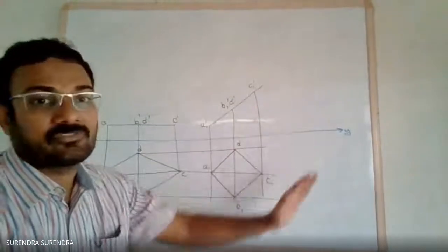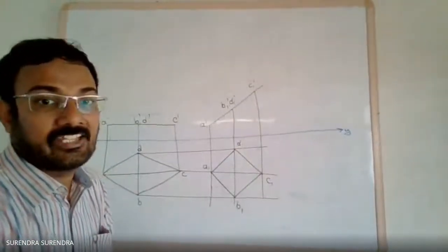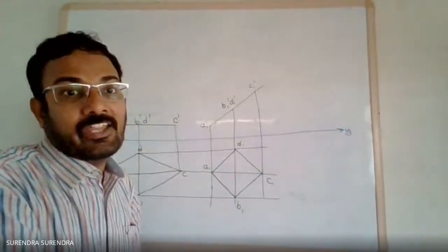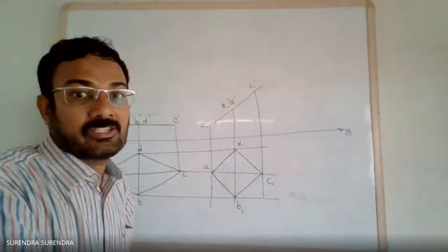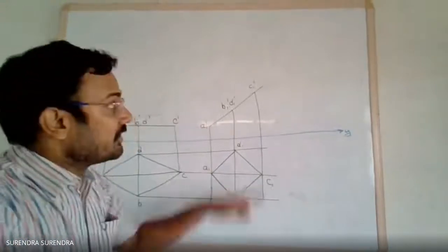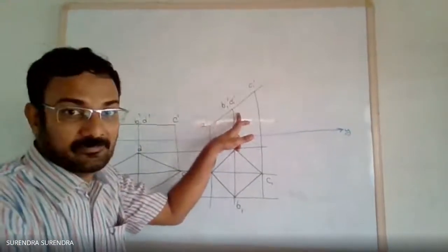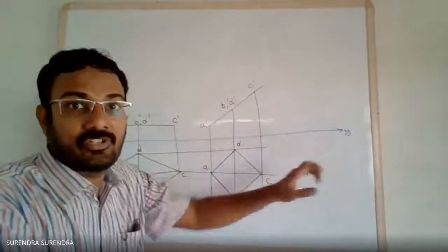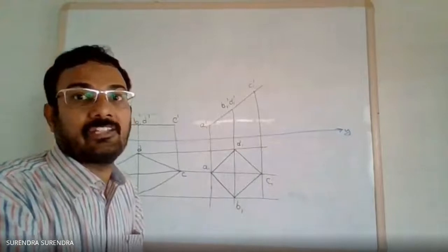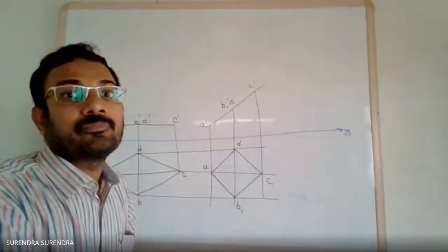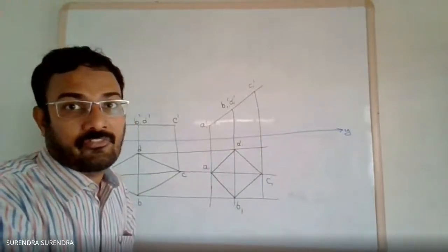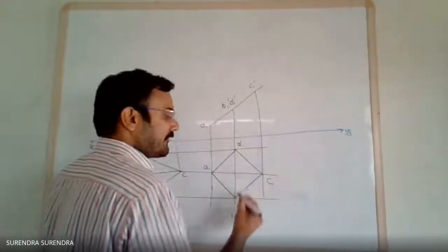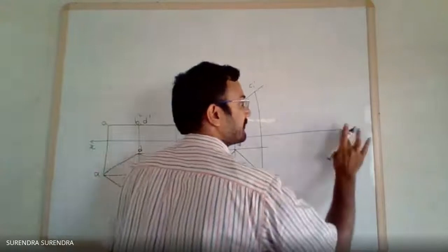So from this we have to draw the third condition, that is making this BD parallel to XY line in top view, means parallel to vertical plane also. Already it is parallel to horizontal plane, but in top view it is perpendicular. So we should redraw this so that it is parallel to vertical plane also. So redraw this same shape, means first draw a horizontal line.